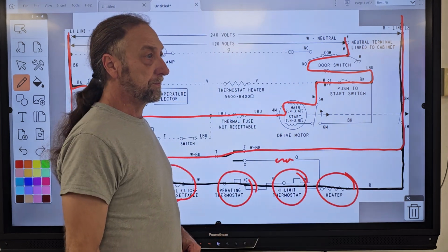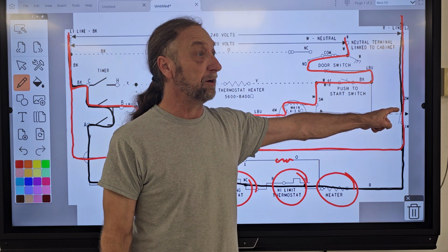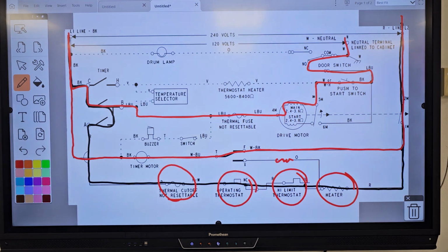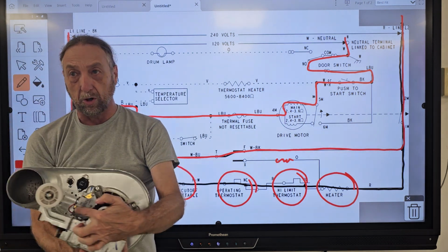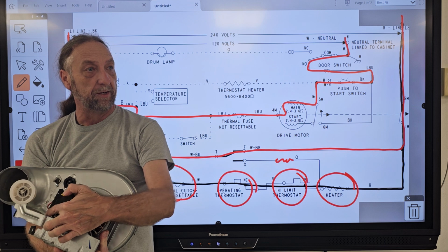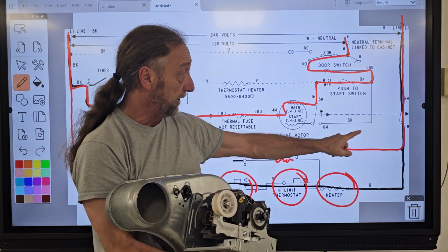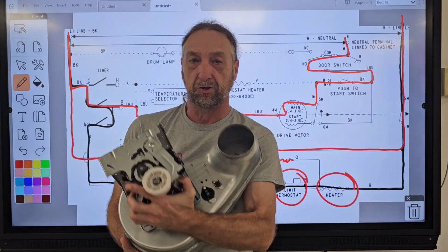The terminals from two, well, no. We don't need the centrifugal switch either. Yeah. But remember I said a minute ago, could the motor stop the heater from working? Yeah, there's a switch on the motor. Let me just get this motor here for example. Okay. So we have a centrifugal switch here on this motor. And if you look closely at these motors, there's all these numbers on here. You got 4, 6, 5, that's actually 3, and 1 and 2. I'll show it on the camera real quick.